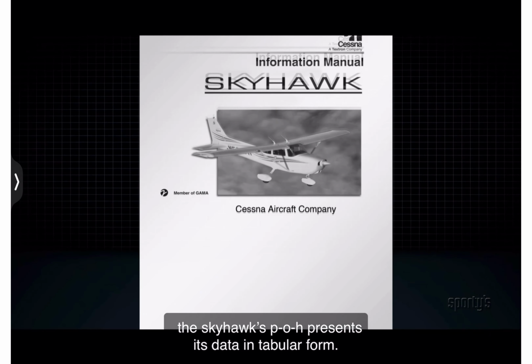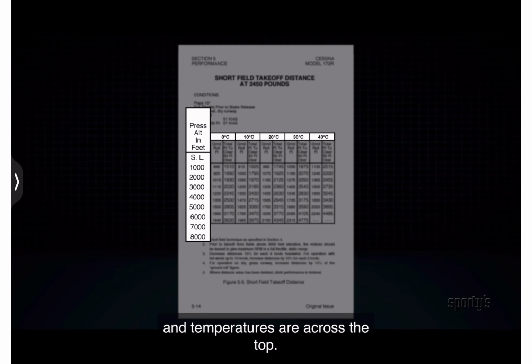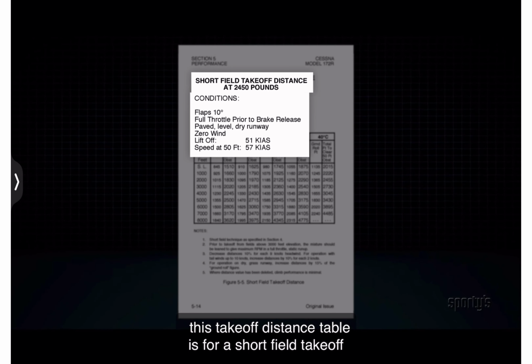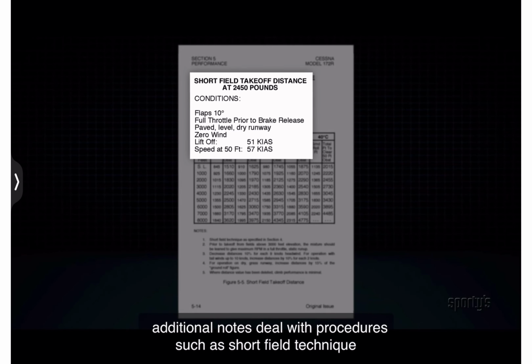The Skyhawk POH presents this data in tabular form. Pressure altitudes are listed on the left side of the table, and temperatures are across the top. This takeoff distance table is for a short field takeoff with the flaps set at 10 degrees, full throttle prior to brake release, paved, level, dry runway, and 0 wind.